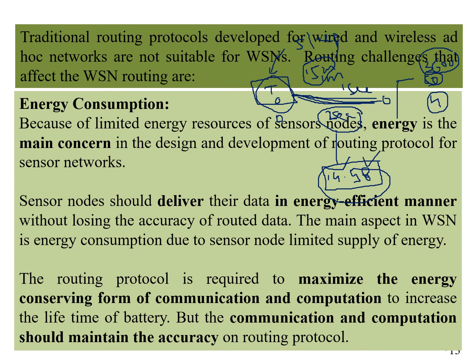In contrast to this node, the gateway is receiving from different sensor nodes. There are a lot of sensors. So this node shouldn't be in sleeping mode. It should be alive all the time because it has to receive the data. So this node needs the power continuously, but those nodes don't need much power and they have to sleep.